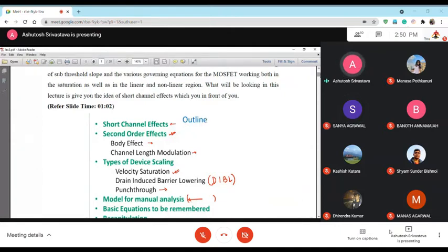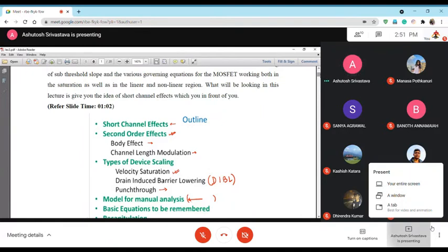Okay. So now we move further. Now that we have talked about transistor operation for digital application, we now talk about what happens when we try to follow Moore's law and continuously push ourselves to achieve that by scaling down a transistor.